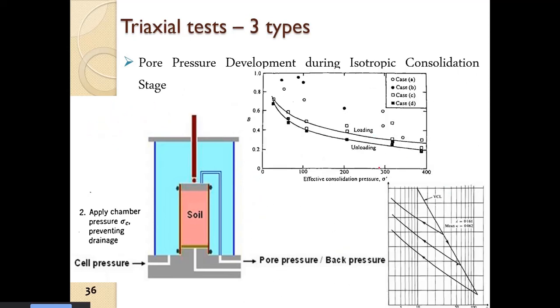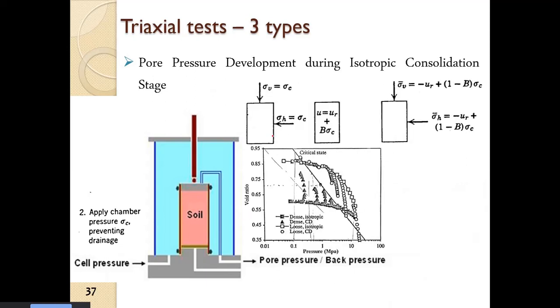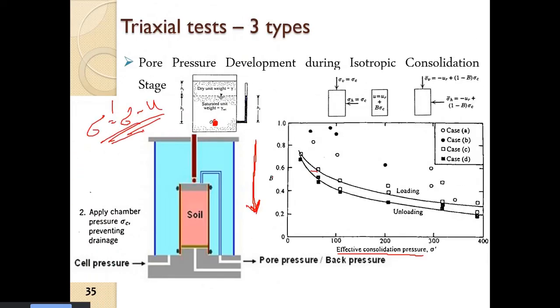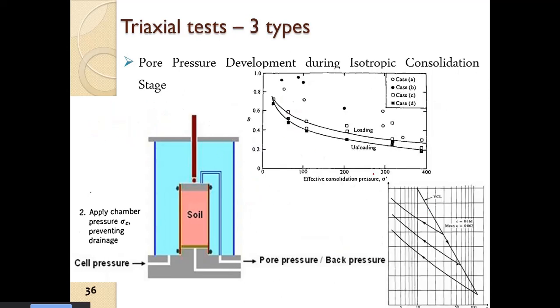So here we see that basically this soil, when we took it out, had already one particular effective stress state. Then the stress state became zero. So definitely this soil is now behaving as an over consolidated soil, until it comes up to the point where it will again behave as a normally consolidated soil. So what is that point?